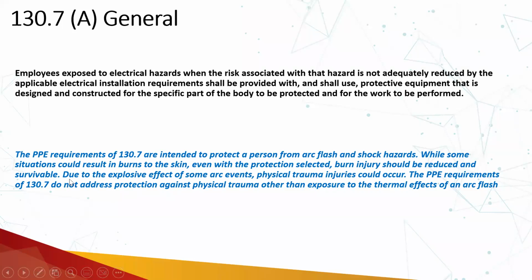While some situations could result in burns to skin even with the protection selected, burn injuries should be reduced and survivable. Due to the explosive effect of some arc events, physical trauma injuries could occur. The PPE requirements of 130.7 do not address protection against physical trauma other than the exposure to thermal effects of an arc flash.